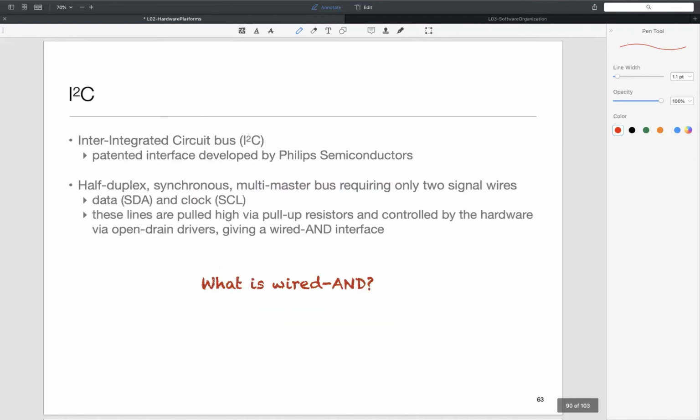So I'm going to skip this. I2C is far more common for sensors because it allows a higher rate interface. It came from Philips, the European company, and the main thing is that it allows a very structured way to address devices as well as to have multiple masters.